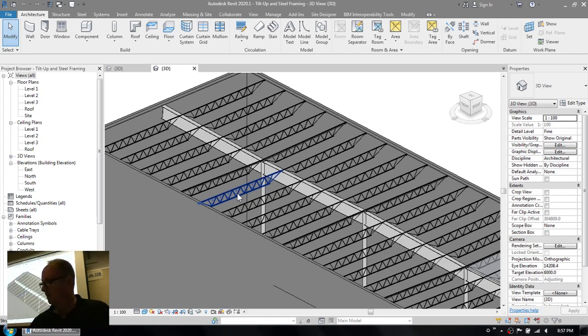Some of you might have dealt with tapered insulation, tapered roof insulation, where the insulation comes at a greater thickness at one end and it gets to a lower thickness at the other. So you're tempting the water to go to a certain location on the roof. Tapered insulation is expensive. So a lot of projects, when they're talking about it, they talk about tapered insulation for about 30 seconds. And they're like, nope, we're going to slope the structure because tapered insulation is too expensive.